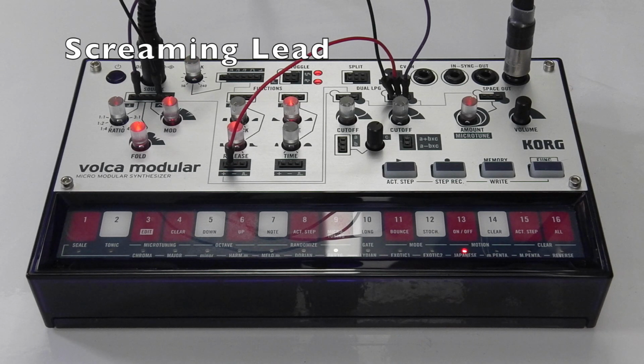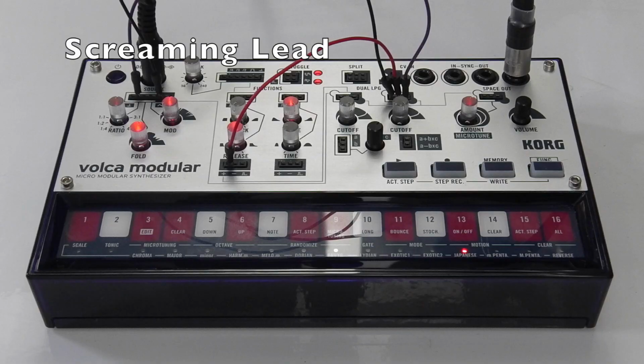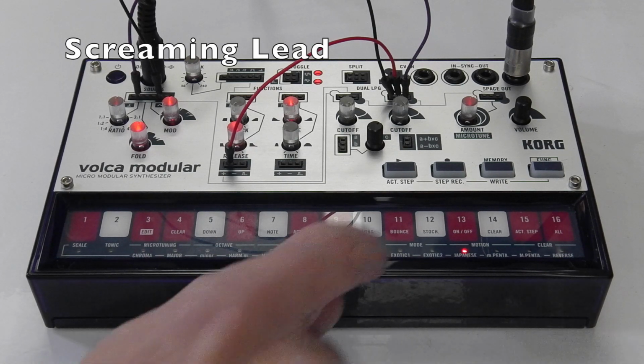In addition to this, the modulator wave is routed to the LPG2 signal input, and the function 1 positive output is also sent to the LPG2 level input. So both LPGs are now receiving the same volume envelope from the function 1. This means that the carrier and modulator waves are combined in the audio signal path, so you hear both waves. You can hear this clearly if the ratio connection is removed, which also creates a useful lead sound.